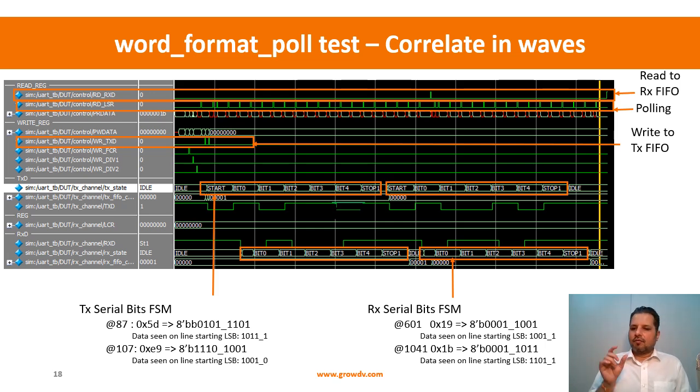So you have to first establish which are the important messages, and once you have established them, you can make a note of it in your own text file. Later, when you have to read the log file, it is not about sequentially reading it. You have to grep out the traffic information from the simulation log file and do the analysis on that. And only after doing that analysis, when you have localized the region to a specific point, some two timestamps, then you come to the waveform.